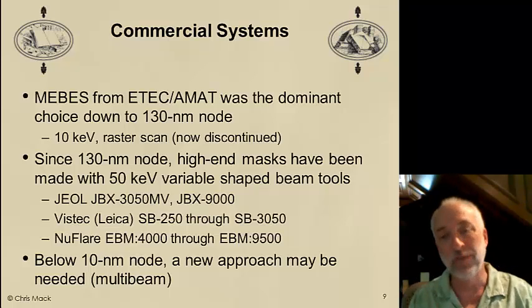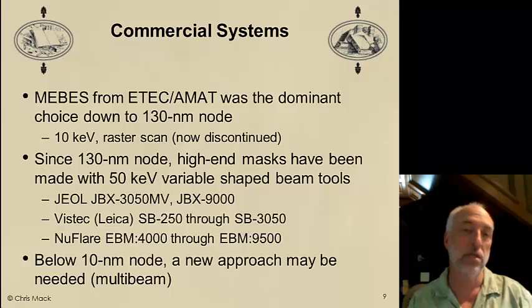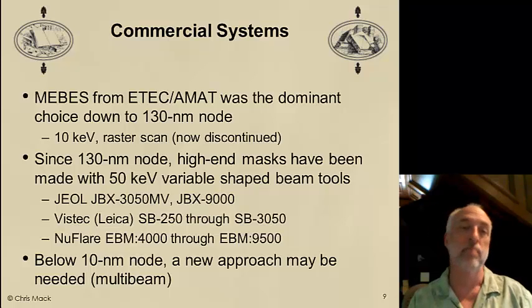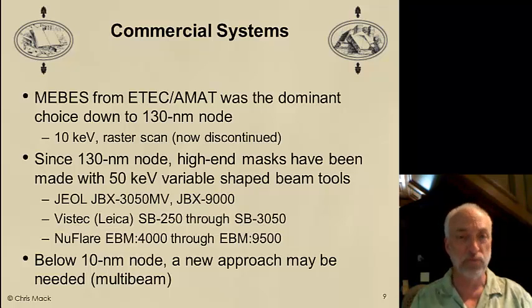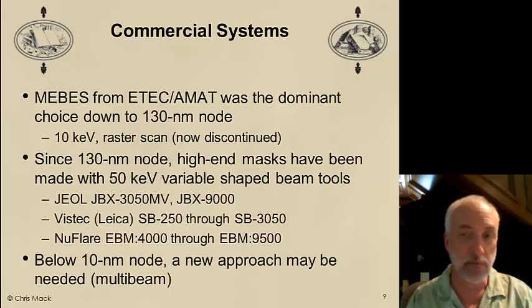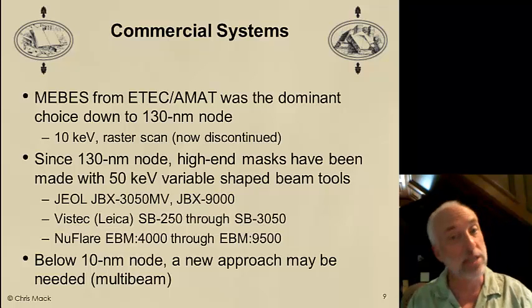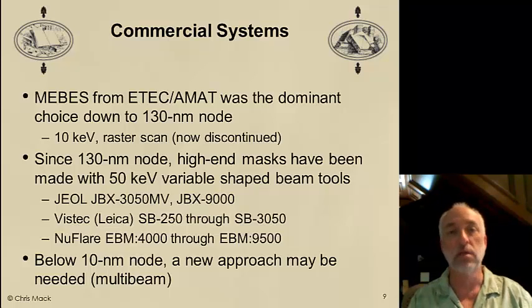Commercially, we've been using e-beam lithography as the dominant way of making masks since at least the 80s. The most popular tool was the MEBES tool from Etec. Etec was later bought by Applied Materials, or AMAT. This was a raster scan system that used 10 keV and was very, very popular for a long time.